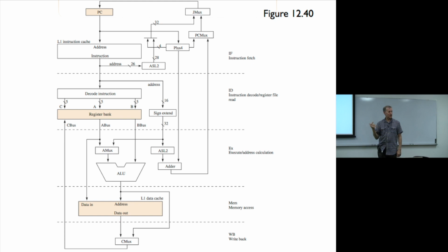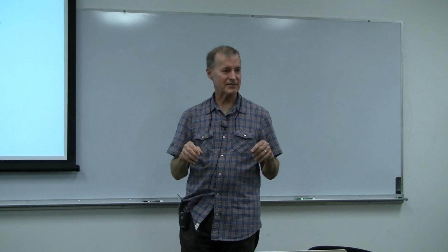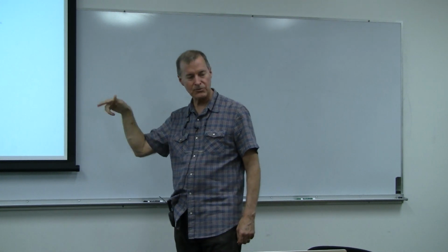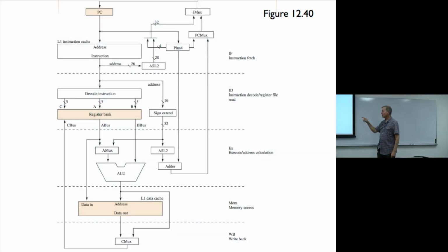Only difference is we saw the registers, right? Do you remember how many registers there are in MIPS? 32. And do you remember how many bits each register contains? 32. So it's a 4-byte, 4 times 8 is 32. It's 4 bytes wide. Now there is a 64-bit version of MIPS, in which case there's still 32 registers, but each one of them is 64 bits wide. Are you with me? But we're just looking at the 32-bit version of MIPS.